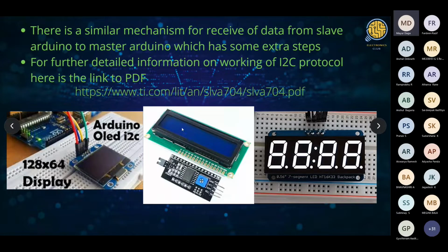For example, there is the Adafruit liquid crystal library for this I2C module with LCD, and this is a 0.56 inch 7 segment LED, which again depends on I2C. You can see here this is the clock pin and this is the data pin, and it has 4 pins. Each LCD 7 segment display has like 10 pinouts, and they are compressed to 4 pinouts with the I2C module.